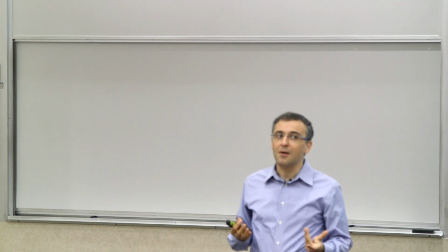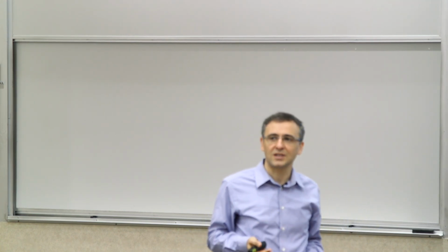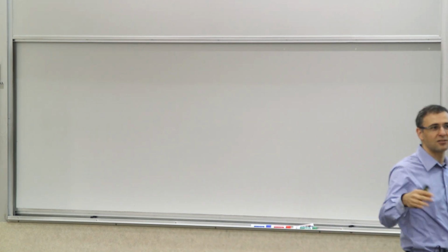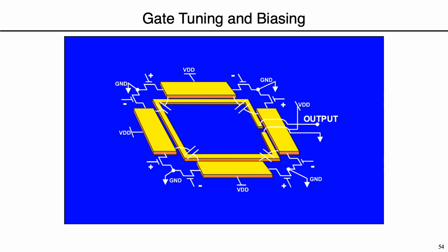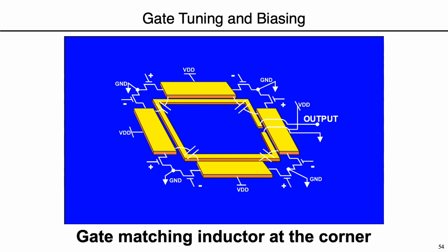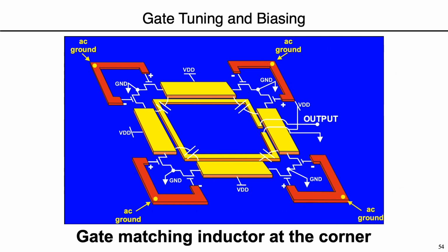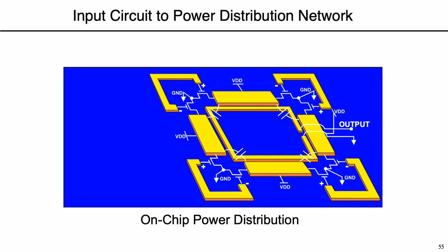Now, that's not a problem because there are no active transistors on the secondary. It's just a piece of metal. And that can drive the 50 ohm load and drive the power that you need to. Now, you need to also think about what you do about your input matching. There are different ways to do this. This is one of the early ways of doing that. If you need an input inductor for matching, you can actually place it between the two adjacent transistors as opposed to across a full slab. And you can get structures looking like that.